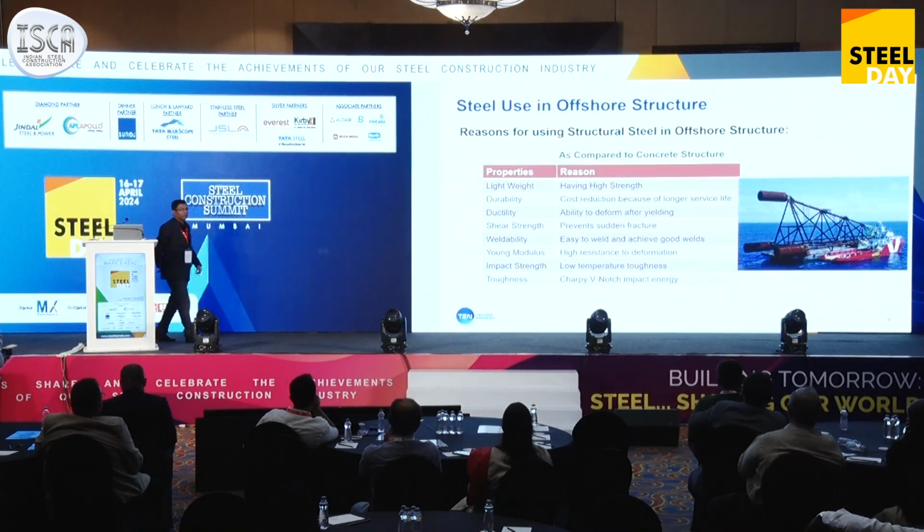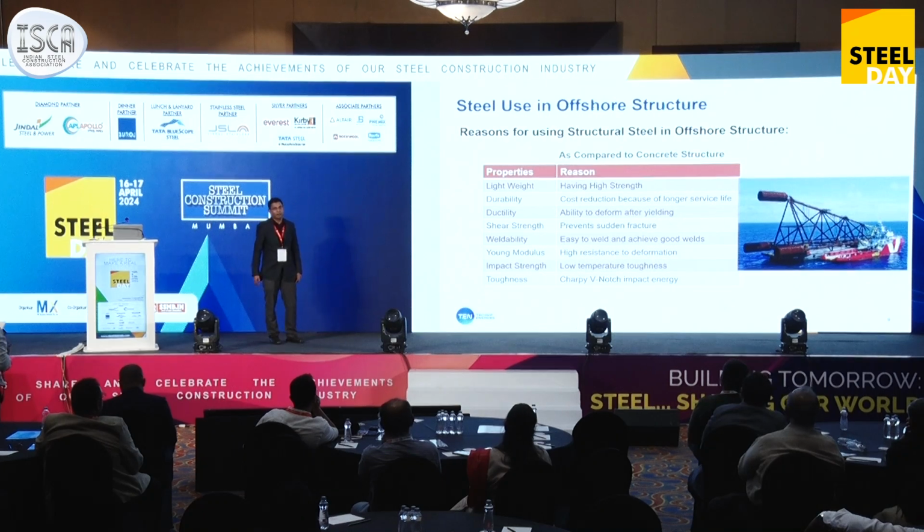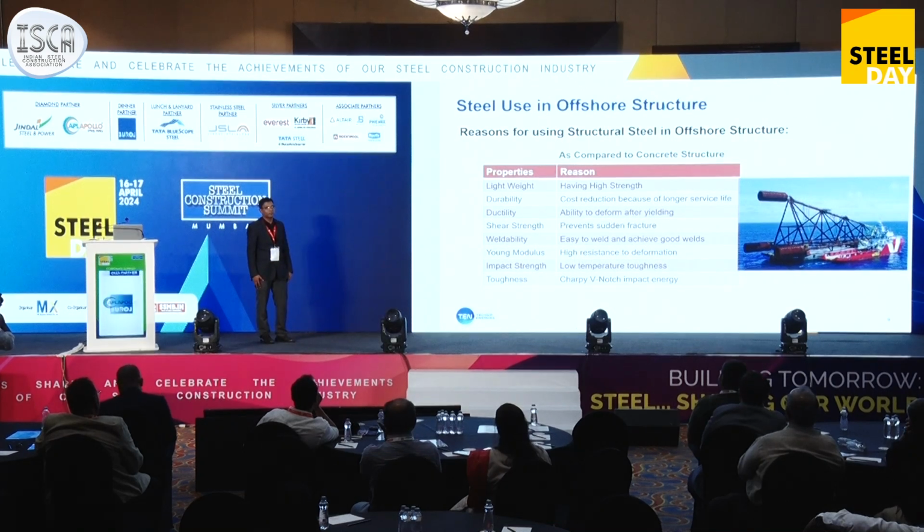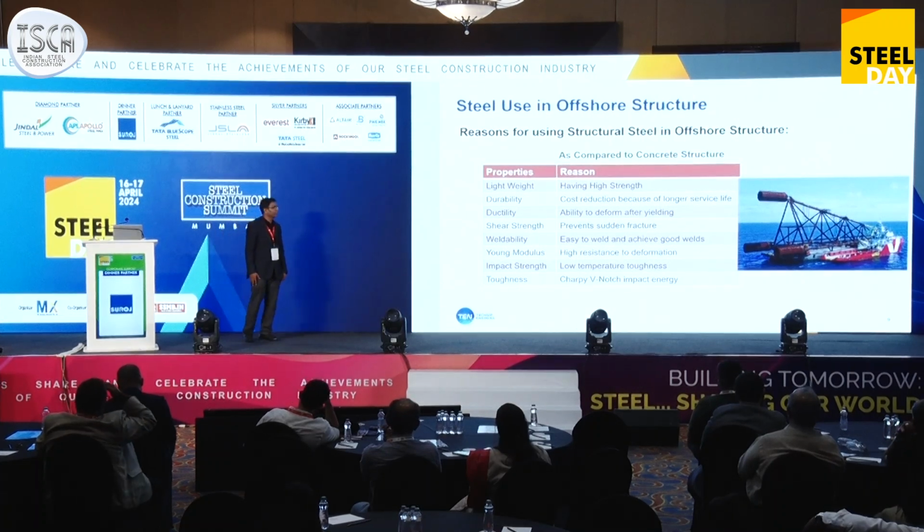Now, why are we using steel in offshore? Most of our speakers and panel members have already given the reasons why we use steel. It has an advantage over concrete due to its light weight. In offshore, weight has much importance. If your weight increases, then your installation cost and fabrication cost increase.